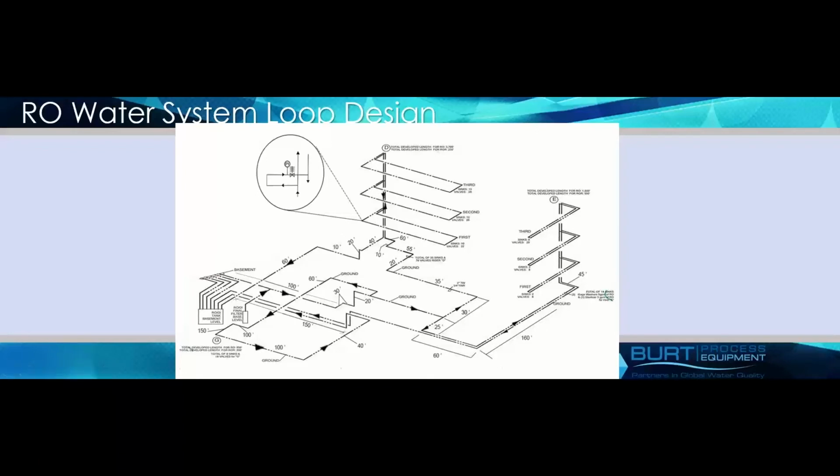Unlike a hot water system, everything in a high purity water loop is balanced based on pressure in the system, not flow. And flow is a tricky thing when it comes to high purity water systems, because what you need to do is maintain a certain turbulence in the system, not necessarily a certain velocity. So a lot of times, what you're looking at is having a flow to compensate for whatever you take out of it, to maintain that particular turbulence within your actual system.